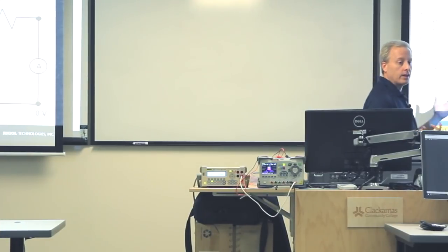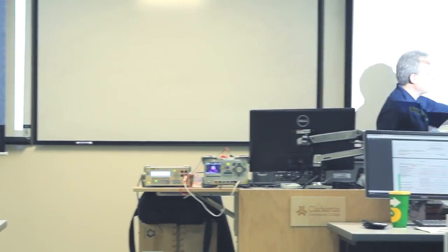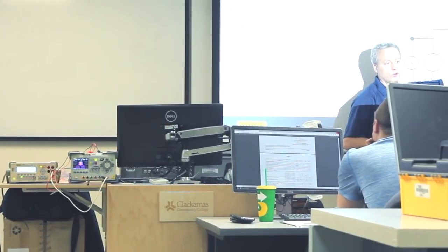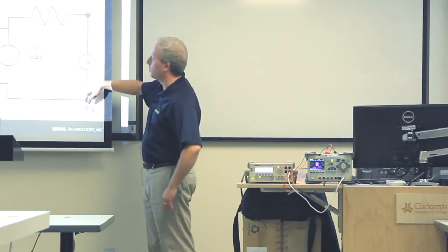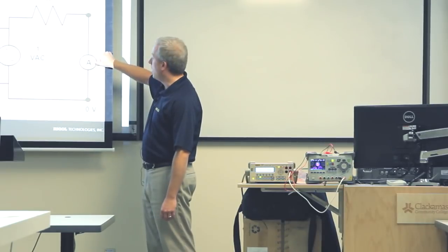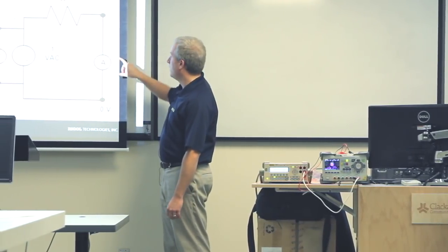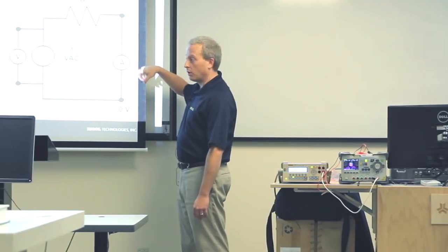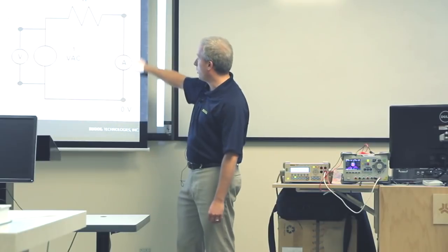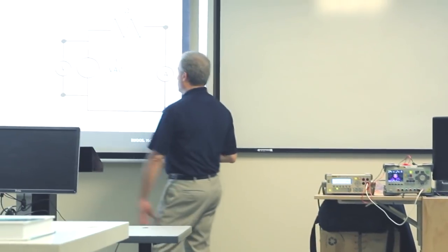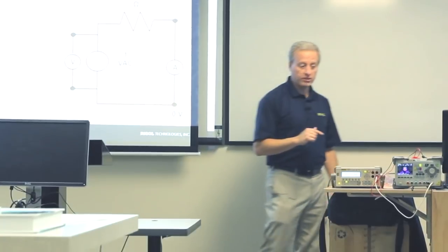The other way we can use the DMM, which is another way it's different than an oscilloscope, is we can use it as an ammeter to make this measurement over here. And as an ammeter, the DMM presents a short circuit. So the special circuitry inside allows the current to flow through uninterrupted, as if there's no voltage developed here. We're able to measure the current that's flowing through directly. So we don't interrupt the circuit, and we can measure both volts and amps directly with a multimeter.